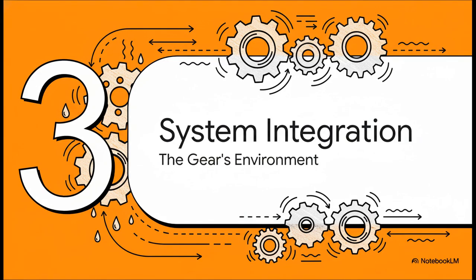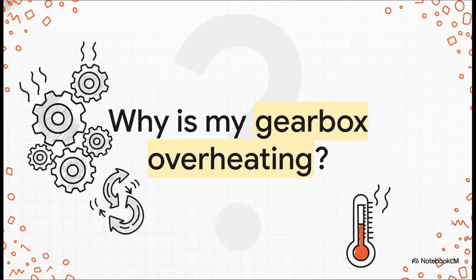Okay, let's talk about the bigger picture. Because a gear never ever works in isolation. Its performance is deeply connected to the entire system it lives in. Things like alignment, lubrication, and heat. If your gearbox is getting hot, it's a direct sign of energy loss. Every single degree of extra heat is just wasted power, and it's being generated by friction and fluid dynamics.